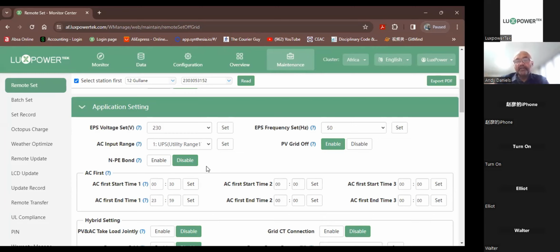So you can bond. There are 2 ways of bonding it, and there are also 2 schools of thought about bonding. Some guys prefer to have a mechanical bond, meaning that when the grid is on, they have a relay, and when the relay is energized, there is no bond, because the output is a pass-through current. Then the minute the grid falls away, or we go to what's typically known in this country as load shedding, the relay will engage and bond the neutral and earth.